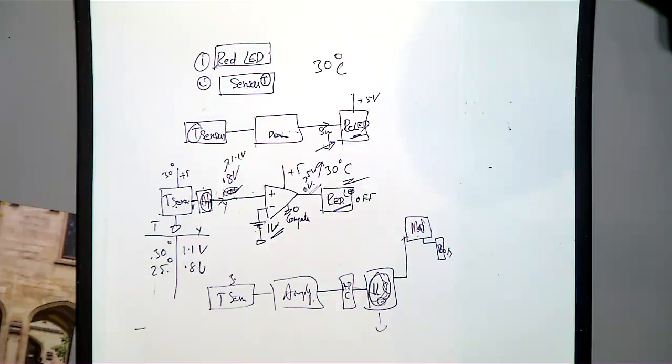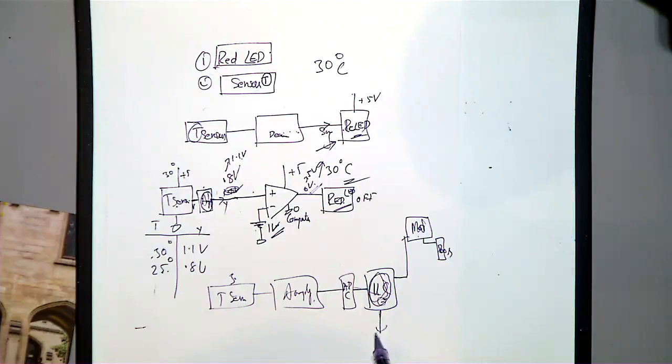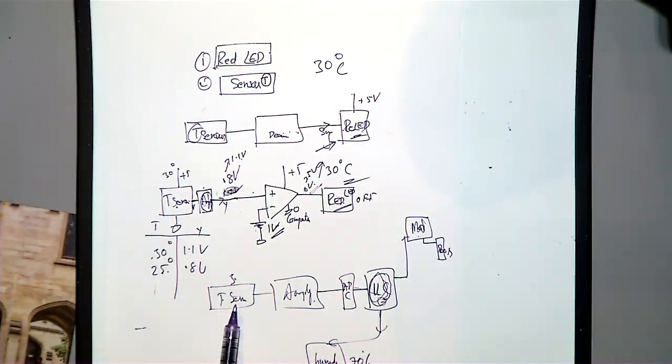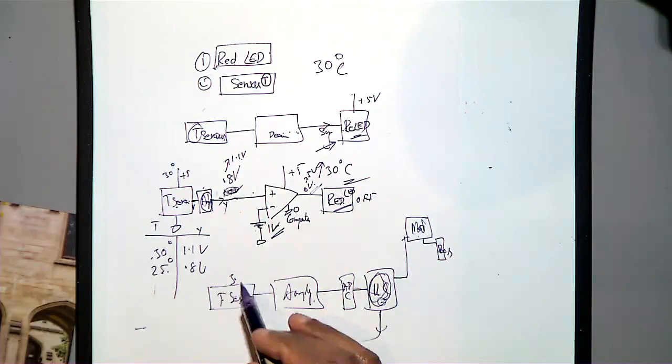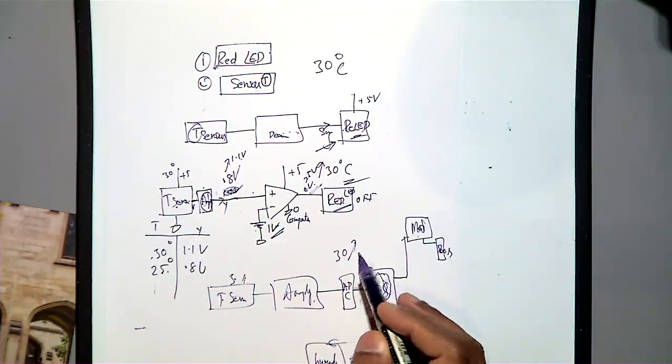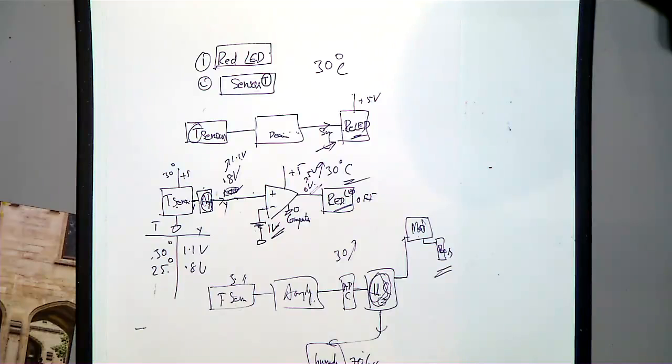For example, again I am going to increase the complexity. Also, I will be here with this microcontroller. So this has got a temperature input. Then it is saying you also take into account humidity. Then humidity, some values, they say 70%. Then you are making another comparison. So not only temperature: when humidity is 70% and the temperature is exceeding 30, then only you make a decision. Then only you open the door, not only with the temperature. Again, you have to make some kind of comparison. Who will do the comparison for you? So in those cases, you need a microcontroller. You will be writing the program.